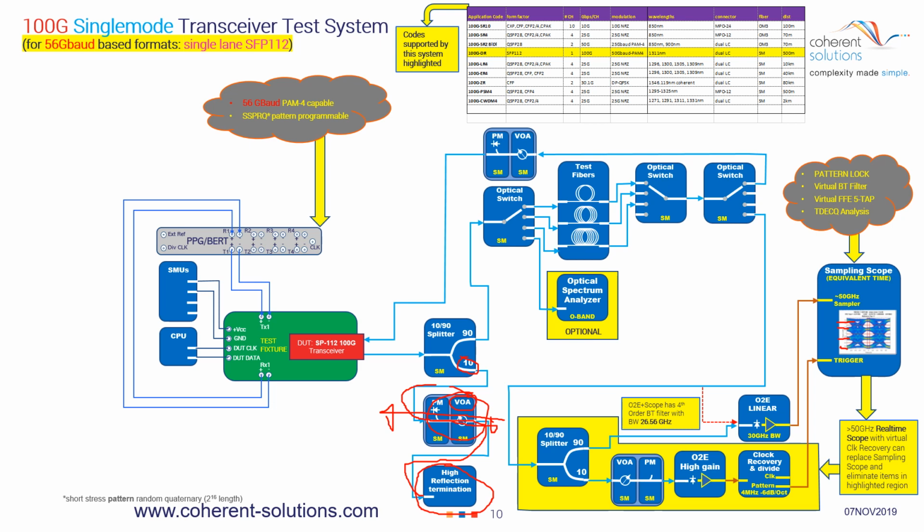The purpose of this signal is to intentionally introduce what is emulating a bad reflection in the network. So although this may be at a power level that is about 20 to 30 times below, reflections can get back into the laser and cause problems. Various standards may have a defined amount of reflection that you must apply while you're doing bit error rate testing or eye pattern testing.